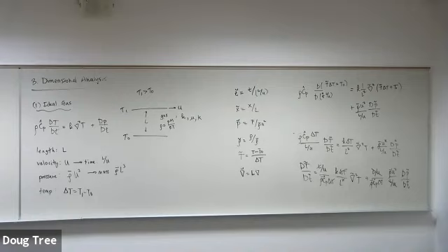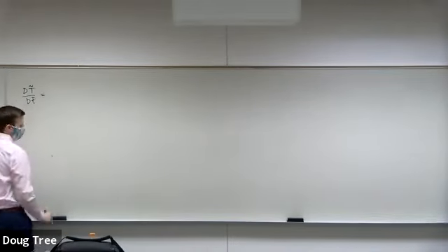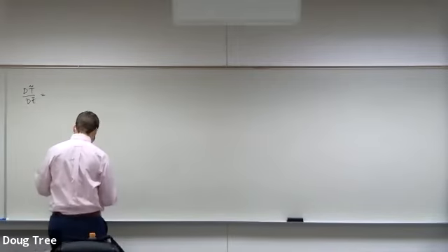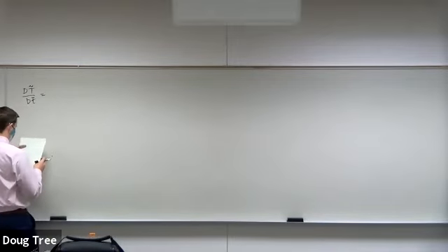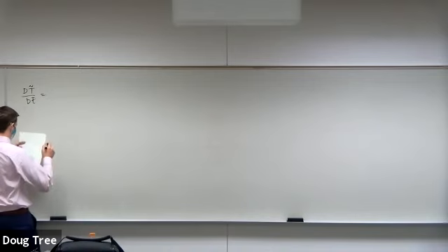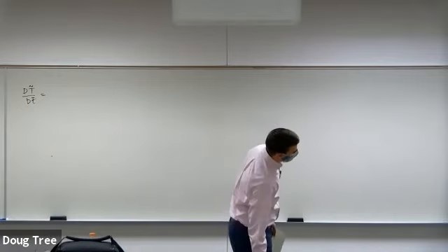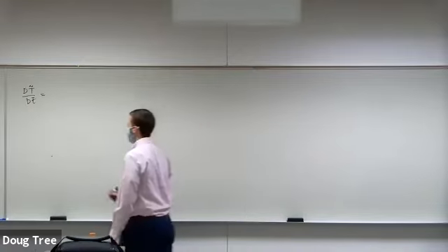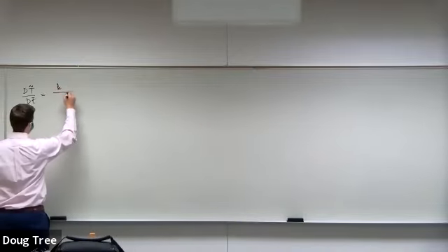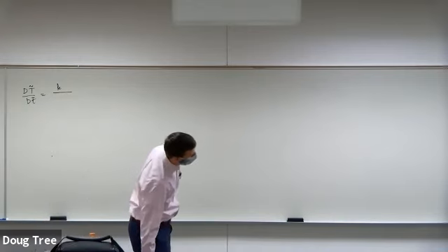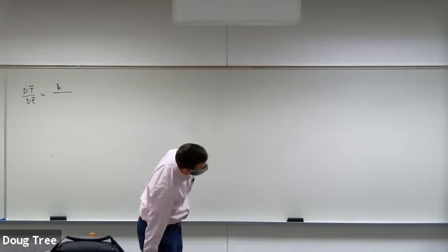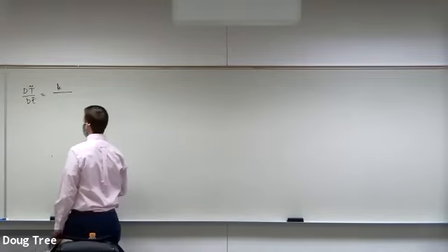Okay, so let's see, I've got dT tilde over dt tilde is equal to, and I can't see all the way over, so I'm going to cheat off my paper. And tell me if I'm wrong. I get K on the top, right? Just a K. Thermal conductivity K. And on the bottom, rho C sub P L U. Is that right?